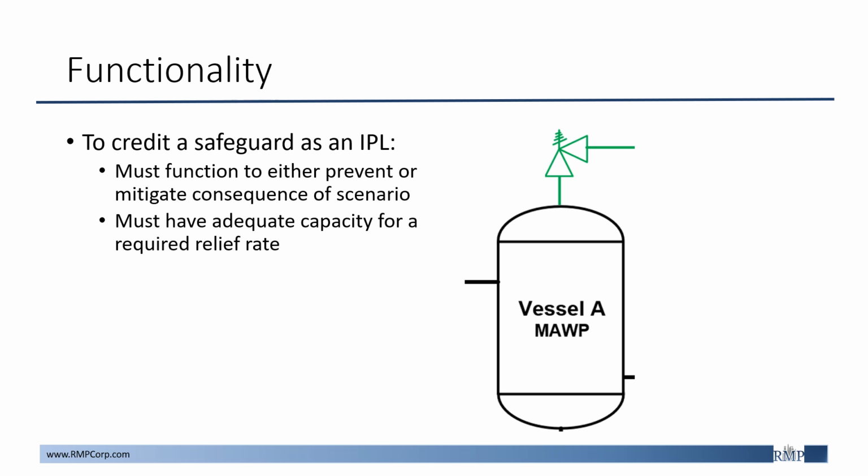If this is overlooked, this may lead to some type of future gap in the design that can lead to costly impacts to personnel as a result of an undersized PSV. So just assuming that a PSV is sized for a scenario is not adequate. If we are crediting this as an IPL, it is very important for us to verify in our documentation that the existing PSV is adequate.